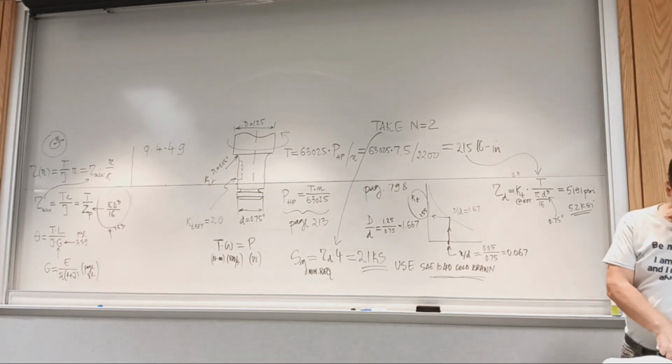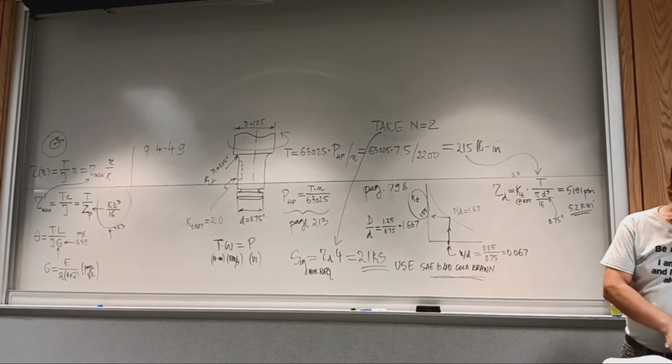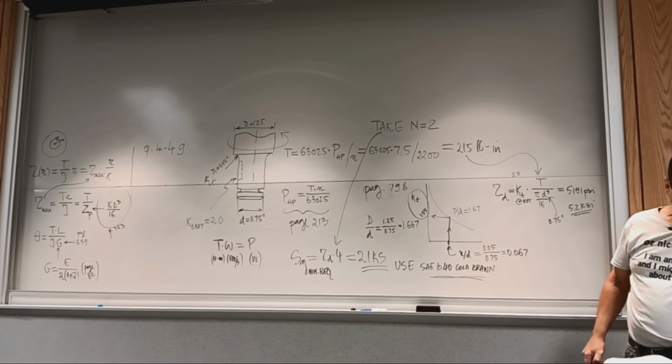All right, problem 50 is on the list. If you look at it, we have a stepped shaft, and it says there's a hole there, and we need to compute the stress for a given torque. And it says determine a large hole that could be drilled in the shaft and still maintain the stress near the hole at or below that at the step.